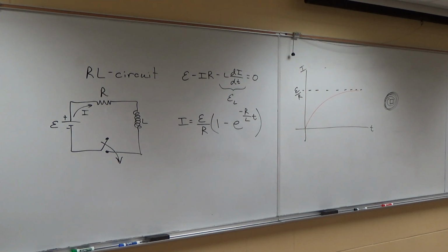In the flywheel, there is embedded a magnet. As that magnet goes by the magneto, you're changing the flux in that coil really quickly and making a spark. So when you're pulling that cord, you're making that magnet fly by the magneto, and you're inducing a spark, and you're also doing a lot of other stuff.